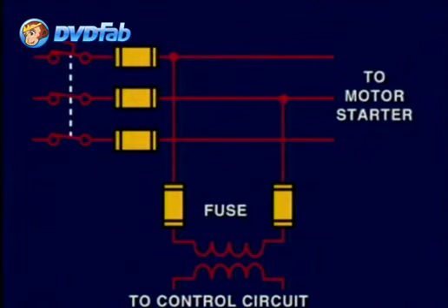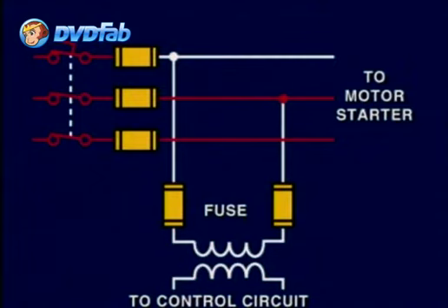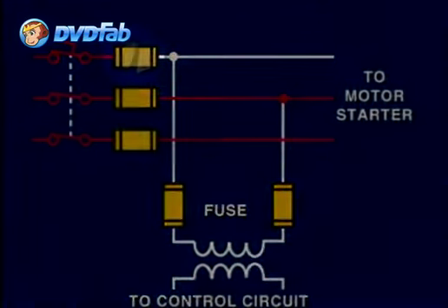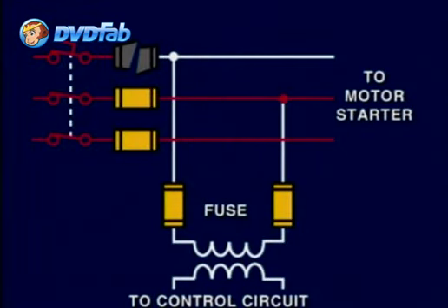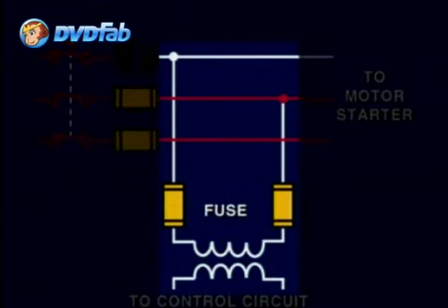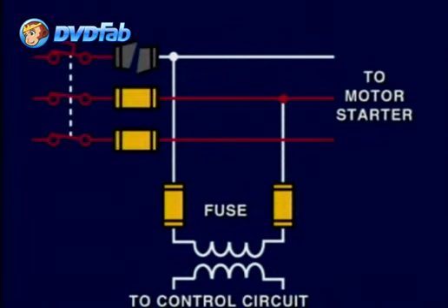If, while checking the power, you discover that there is no voltage and that one or more of the fuses is blown after the disconnect, you can assume that a potential short has occurred in the circuit or in the motor itself. If the power feed has a protected branch circuit for the control circuit, a short in this area can be eliminated because it is protected by its own fuses. Note, however, that this control circuit will have no power.